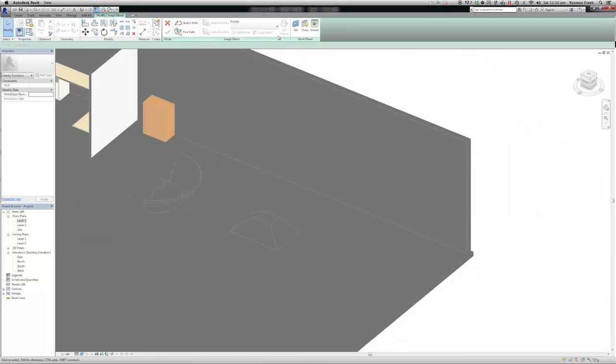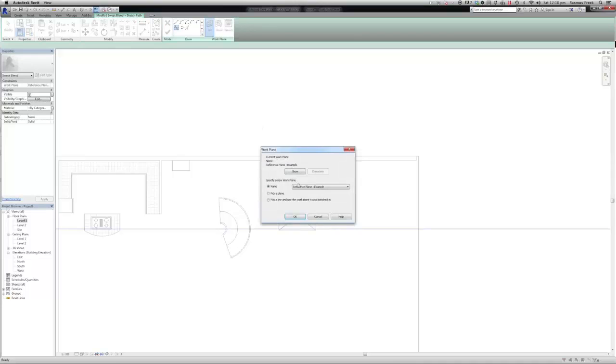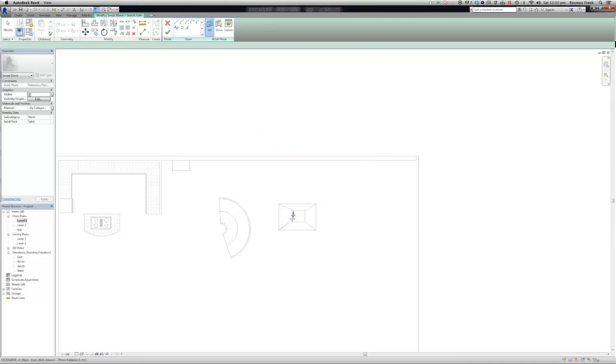Now let's create a swept blend. To begin, sketch or pick a path for the sweep. For this example, we will sketch one. The path we create can have as many curves as we desire. However, it can only be made from one continuous line with no sudden changes of direction. Finish the path.